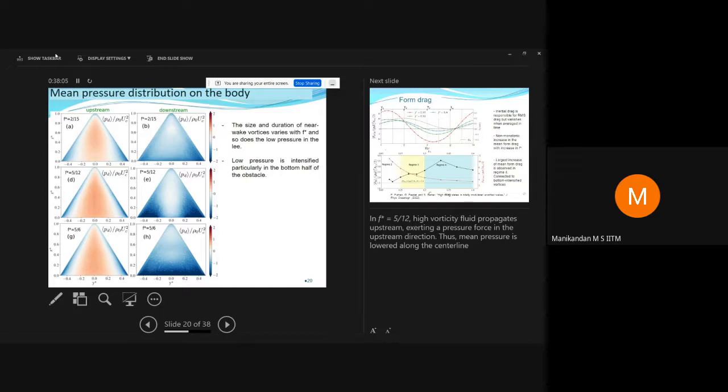It's just that in the stratified wake, the stratification effect keeps increasing. The local Froude number keeps increasing. So vortex stretching and so on. Yeah, the local Froude number is changing. The wake is increasing laterally, and within one wavelength of shedding, not one wavelength. So we got significant turbulence all the way till maybe 5 to 6. Depends on what you call significant. But 5 to 6 diameters, that's quite a bit of turbulence. Yeah. Sure.